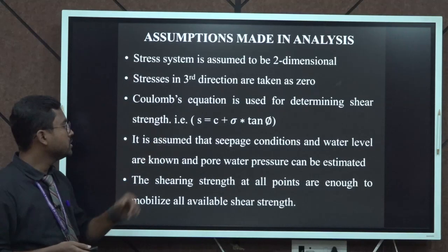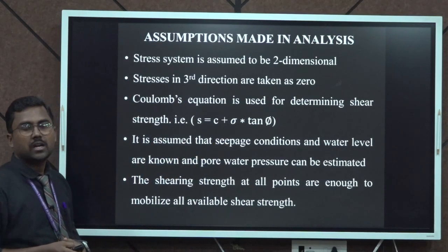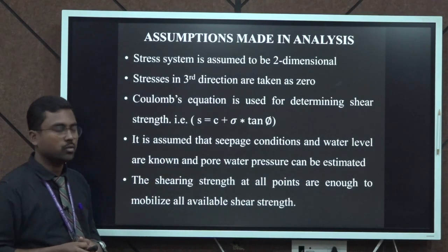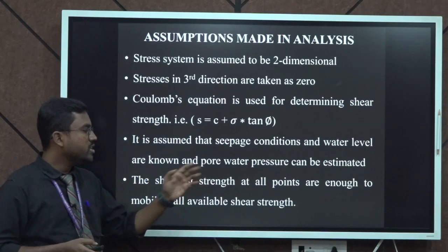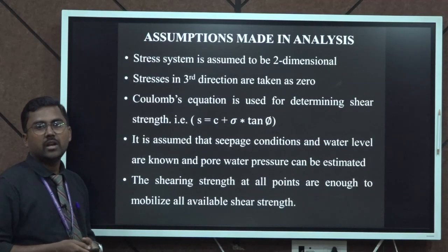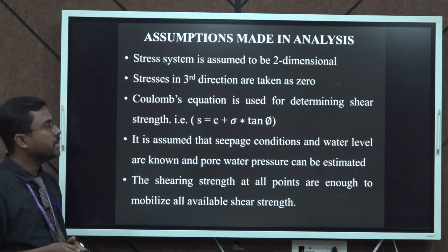We have to calculate all these three parameters, and it is also assumed that the seepage condition and water level are known parameters, and pore water pressure alone we have to calculate. And finally, the shear strength at all the points is enough to mobilize all the available shear strength, and these are all the assumptions we have to make before doing a slope stability analysis.